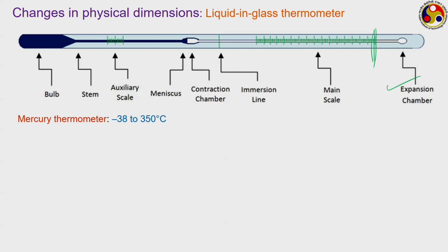While the boiling temperature is more or less okay, the freezing temperature is quite high compared to several applications. We can lower this freezing temperature a bit if we use a mercury thallium mixture, then it goes to -56 degrees Celsius, which can be sufficient if we are looking for, say, weather temperature measurement in the toughest of conditions, but if we are looking for certain kinds of cryogenic applications, this is still quite high.